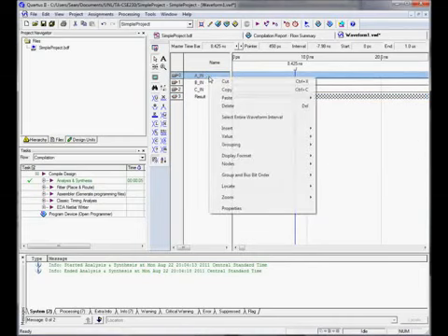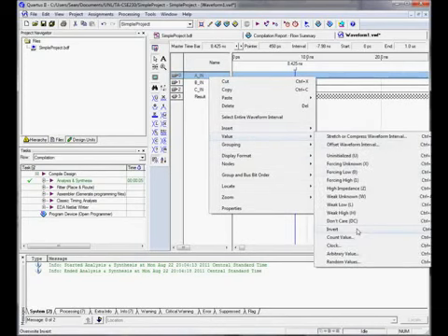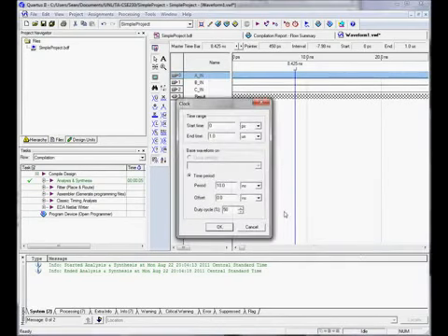We're going to take this and right click and go to Insert, or excuse me, we're going to go to Value, and we're going to go to Clock. Clock allows you just to turn it from high to low, high to low, high to low. There's all different options in there, including ones that are arbitrary or completely on or completely off that you can play around with. So we're going to make this kind of quick. We're going to say that it's a 5 nanosecond period with a duty cycle of 50%, so it's a square wave.